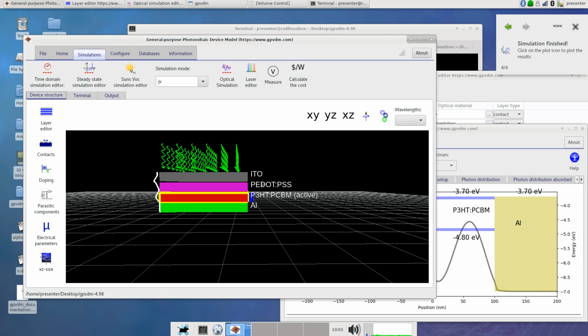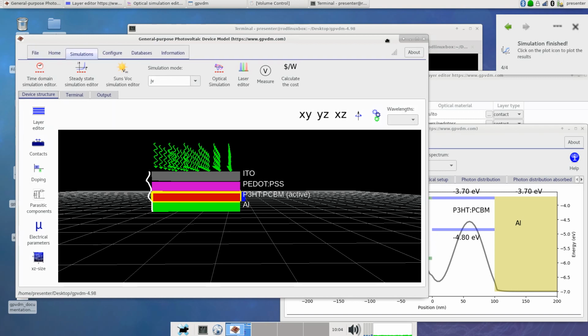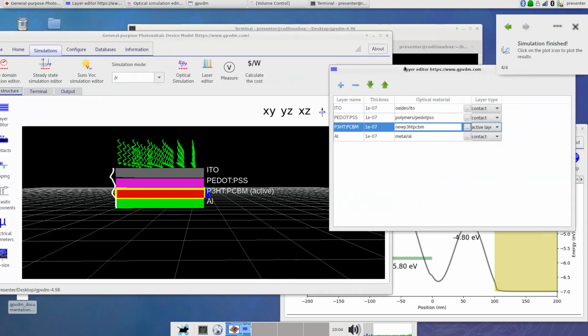We can probably just model it with a resistance. There's no point in solving all the electrical equations over that sheet. And the same with the aluminium, it's just a bit of metal, not that interesting. We don't need to bother solving electrical equations over it. So to save computational time and time setting up the model, we say, let's just simulate one layer electrically.